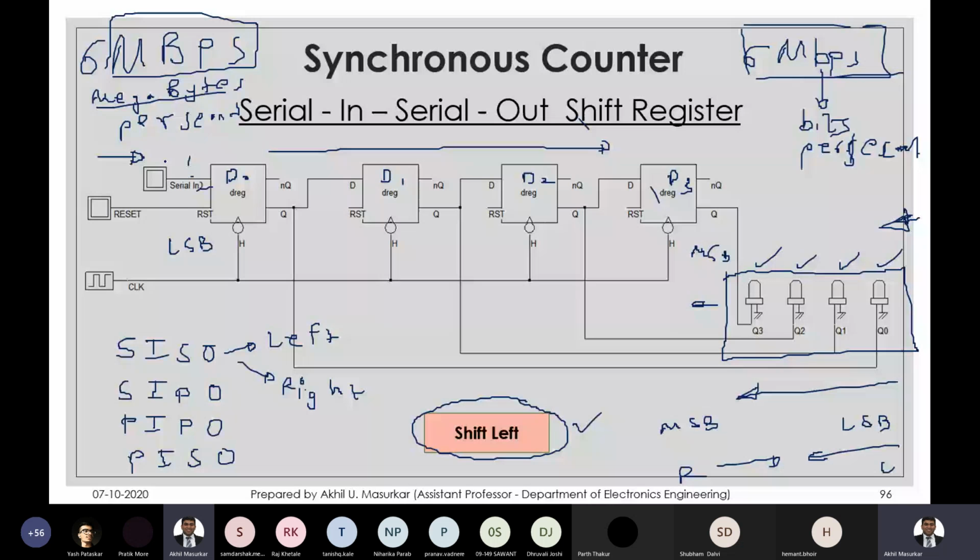So if you want to build a 64-bit register, you will require 64 flip-flops, and each flip-flop will have a JK flip-flop inside it, which is operating in D mode. So there will be around 8 or 9 gates, and each gate will have around 6 transistors. So 8 9s are 72, into 64 of them. That's a huge number of transistors for a single 64-bit register.